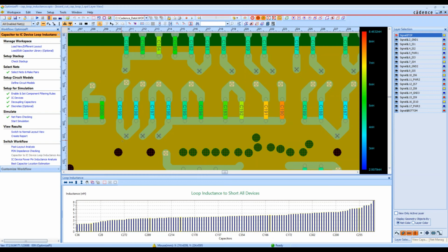What type of setup is needed to make this process work? The setup that's needed, we showed a number of different processes today. For our DC analysis, you need your board file, of course, you need your VRM source, and you need your sink currents. Those are the majority of things you need. There might be other things here and there depending on your setup.